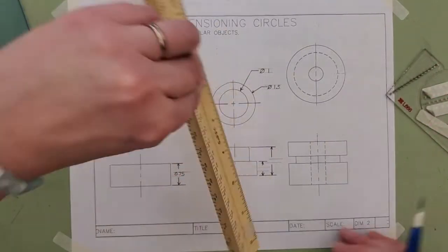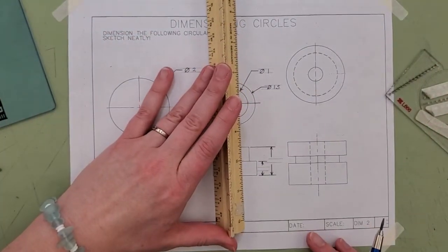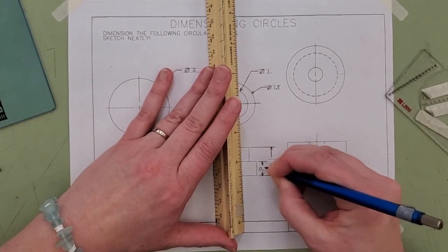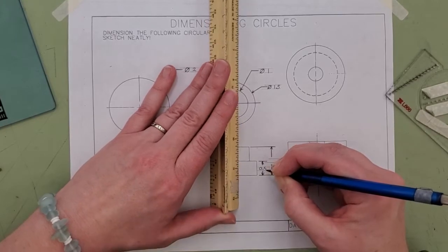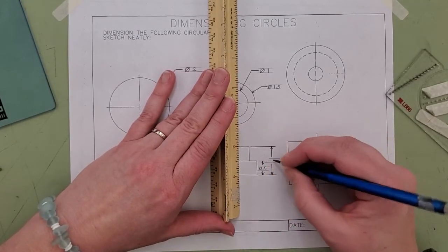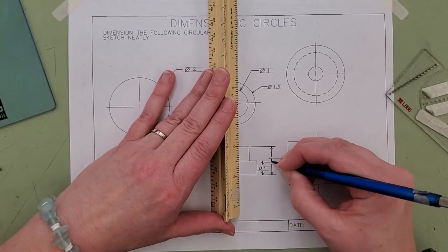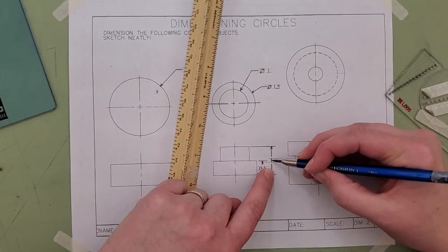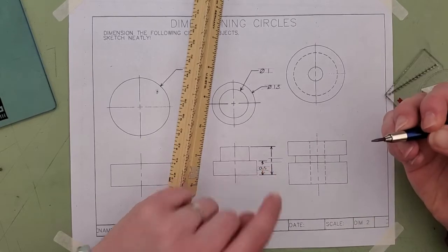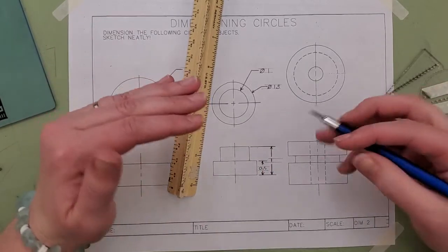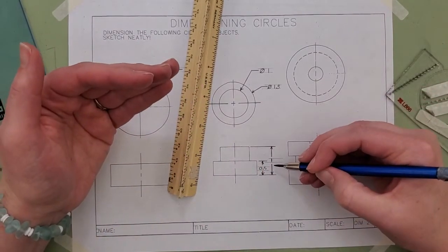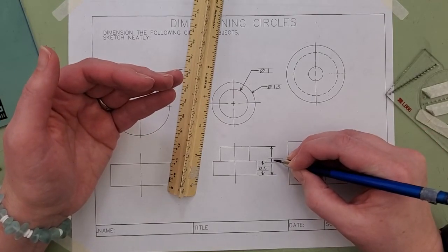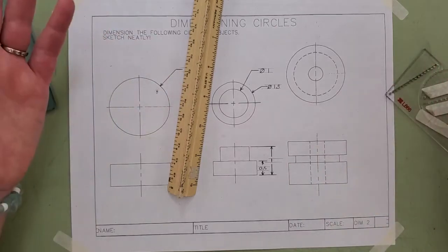So let's see here. This is 0.5 inches, and this is 1 inch. Now guys and gals, be careful with the 1 inch. If you have those arrows touching your lettering lines, then it will look like just a solid line. Okay, so you need to make sure that gap exists, or you might want to move the 1 out to the side just a wee bit. Not too much though.